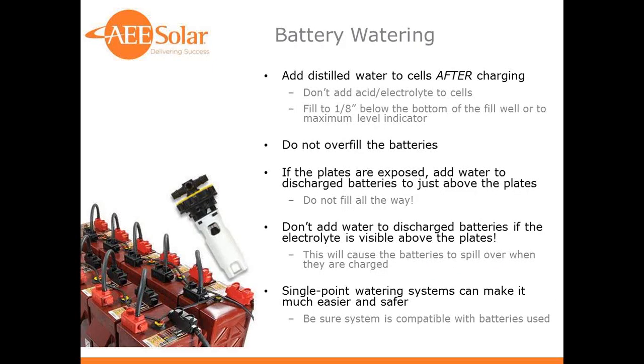And battery watering is a very important thing. Only add distilled water or deionized water to lead-acid battery cells. No well water, no tap water, no stream water, creek water, no ponds. It needs to be very clean water. Obviously, any minerals or other contaminants that are dissolved in the water are going to affect the chemical reaction in the battery, so we don't want to do that.